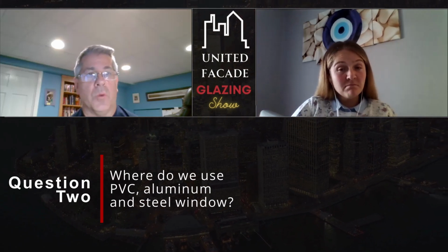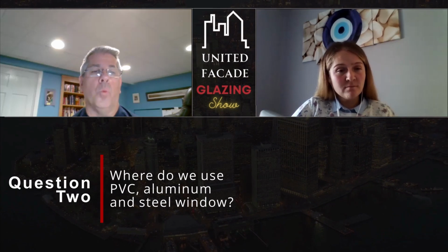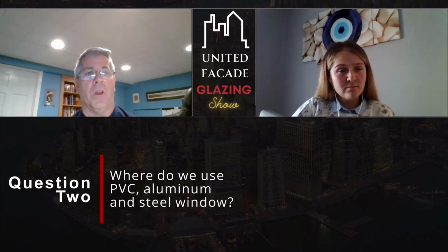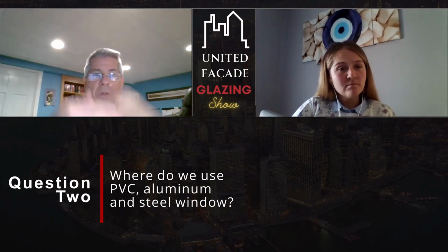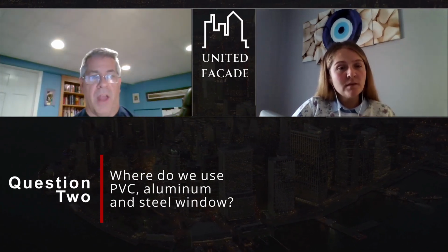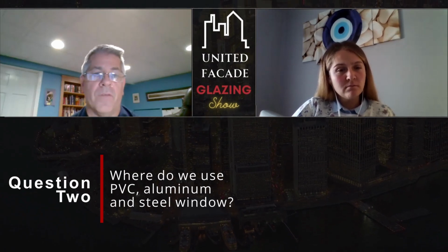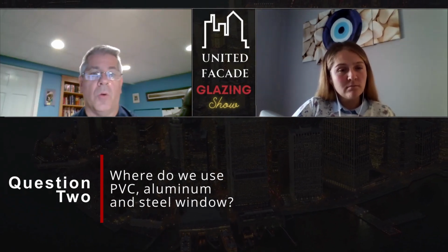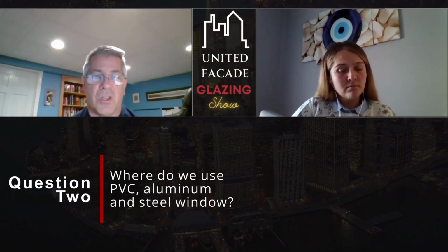It's lighter weight. So when you're making these windows, weight is a consideration when an architect's designing a building. When you've got a 60-story building, you're putting all these windows on top of each other. There's a lot of weight that you're hanging on this building. Aluminum is probably a third of the weight of steel. So in doing so, you're able to design different sizes.